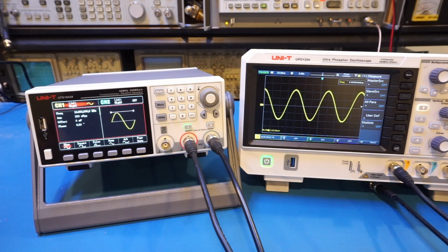Another potential benefit is when generating sinusoidal waveforms. In theory, the higher the vertical resolution, the higher the fidelity of the generated quantized waveform, and in theory that translates into better spectrum purity. Now, I said in theory because there are other factors, such as filtering implementation and the phase noise of the DDS. They also play a crucial role.